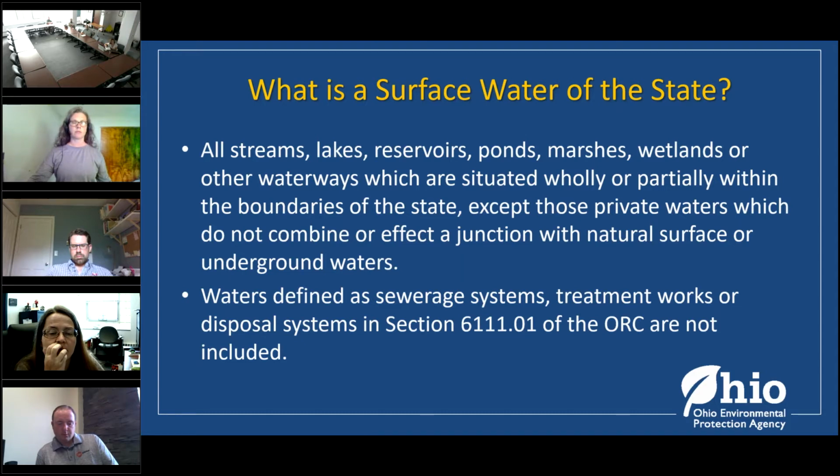But there's an exception. There's a higher risk when we have soil disturbance close to a surface water of the state. So this performance standard asks that in those situations, a method is applied to the soil, some kind of cover, within the first 2 days instead of 7 days.